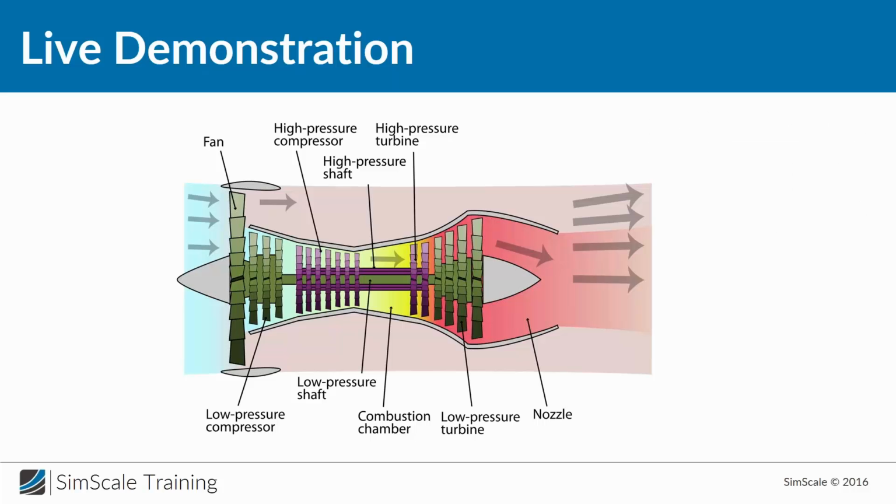And in the end, what a jet engine is doing is quite equal. First of all, we have here our combustion chamber. You can see here, here will be the combustion chamber. And basically, what is the combustion chamber doing? The idea is that heating up the incoming air to a high temperature will expand it, and that will create a jet. Right. And for optimum and very efficient combustion, I need high temperature and high pressure of the incoming air. And therefore, I have here a compressor stage.